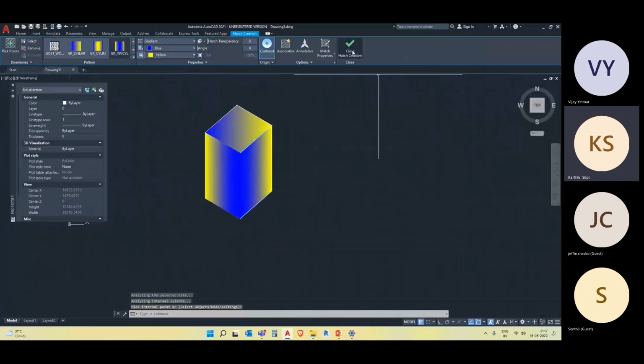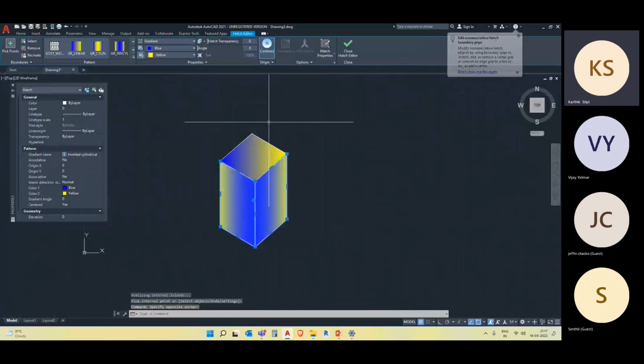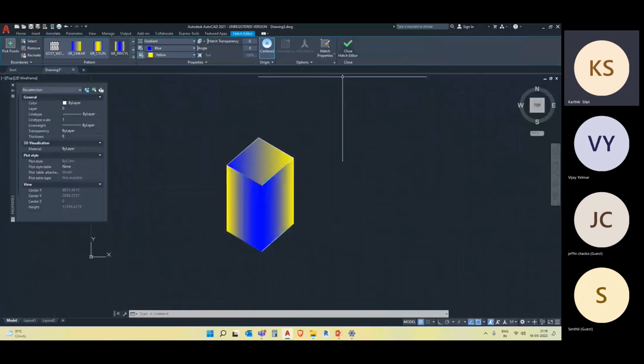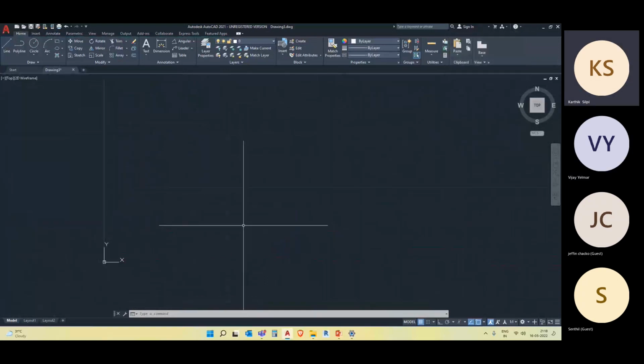So like this. So here, this is a representational image of something which is drawn in the form of 3D. It will take time if you draw it as a default thing. So what AutoCAD has given us is a separate environment for us to draw isometric drawings. That is the isometric view. In order to go to the isometric view, you have to simply go to this here. If you turn on this with a click, you can see automatically the grids have been changed. Earlier it used to be straight.